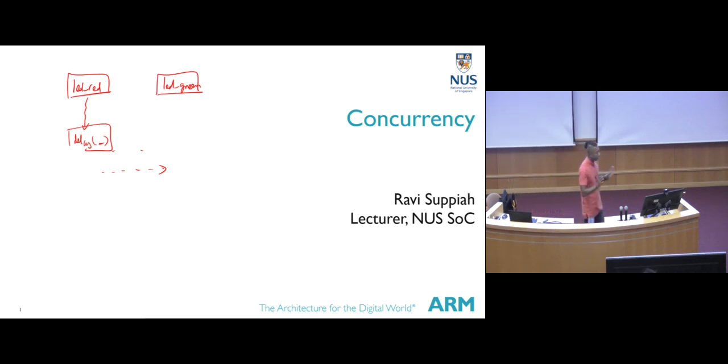From now already you see that the way we have to think about designing the whole system and the architecture will change. Up till now we are very used to having what we call a super loop. We have a while loop, and inside that while loop we have task 1, task 2, task 3, task 4, and so on. Then we have interrupt 1, interrupt 2.